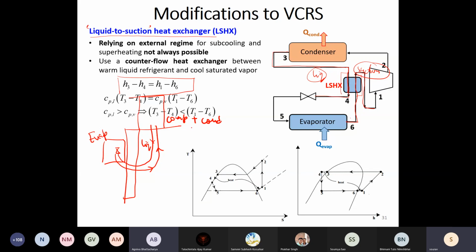And then you would see that the AC mechanic puts in an insulation, a black colored insulator on that, and then he puts an insulation tape on that, and then pushes the pipe out through a hole in the wall. This is to prevent the outdoor heat heating the suction line. The liquid line is already close to the ambient temperature, so there is not significant heat transfer between the ambient and liquid line. But the suction line is already very cold because it is at a temperature close to the indoor temperature. So there the insulation is very, very important.